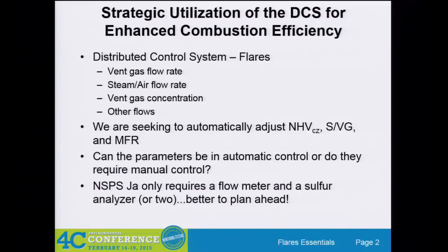We're finding that when we're doing these control systems, you're looking at a significant number of additional tags that are going to have to be created for this system. We've sat around and thought of all the different tags we could think of, and you're looking at at least 50 to maybe 150 new tags to implement this.